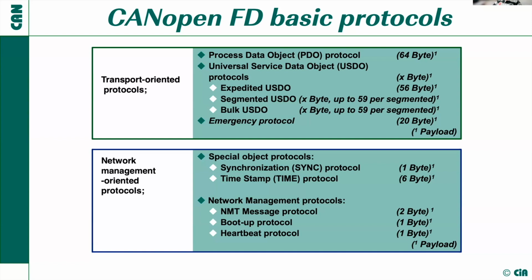And also when it comes to the services, we were analyzing where do we really benefit from CAN FD functionality. And there we saw, okay, in all the network management oriented services like the sync message, like the timestamping, like the management of the network management state machine, we just need a couple of data bytes and we are not limited by the CAN classic data frame. So we wouldn't gain too much, but we would change look and feel. So we thought it's wise to keep these services stable.